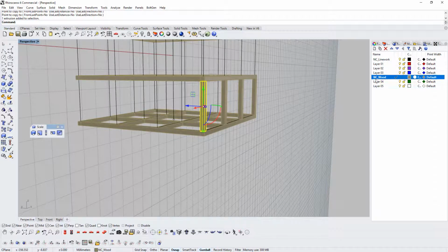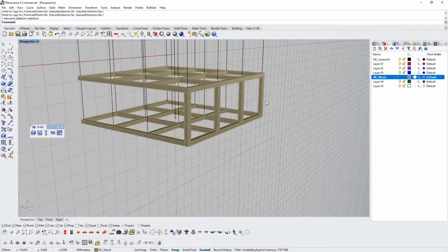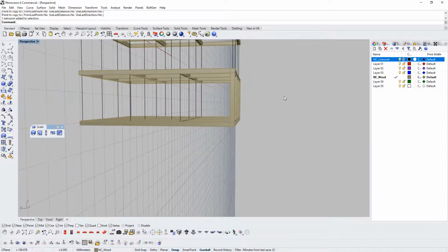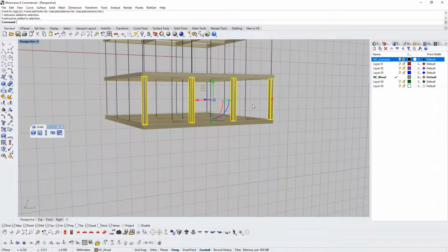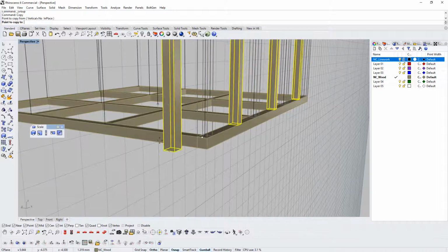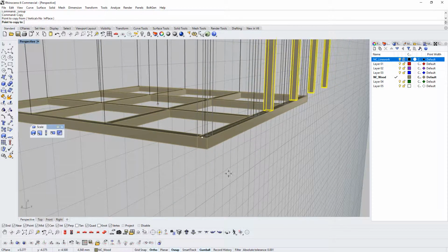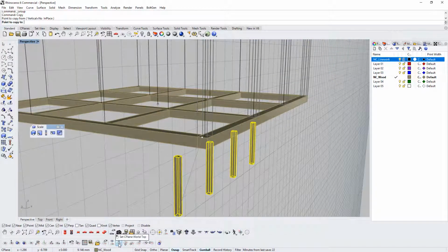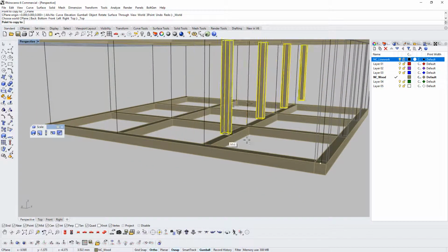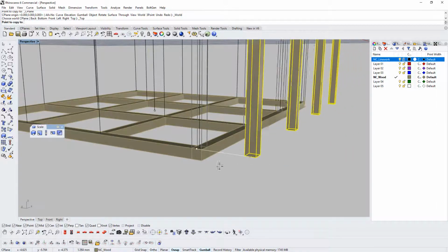Now we're going to grab those again. Now what you can do is, since we're not using the line work as copying, we can go over here and hit this little lock button right here, and that will lock it. So now we can't actually click that layer. So you can highlight like that, group it, and now we're going to copy those over from the midpoints, right? Oh, it's not locking into place because the plane's that way. So we're going to go down here to the C plane again, hit it on top view, and now we see that we can go in that direction.